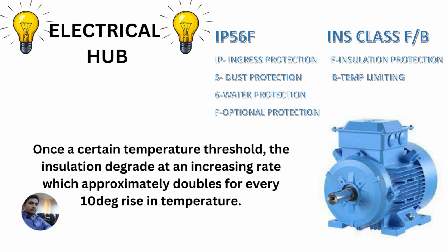So, first, let us see what will happen if the quality of the insulation degrades with the rise of temperature. For every 10 degrees centigrade rise in the temperature, the life of the motor will reduce by half.